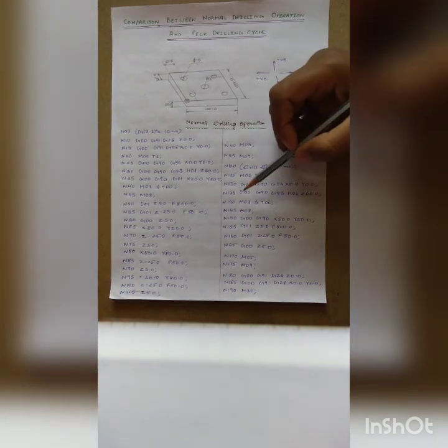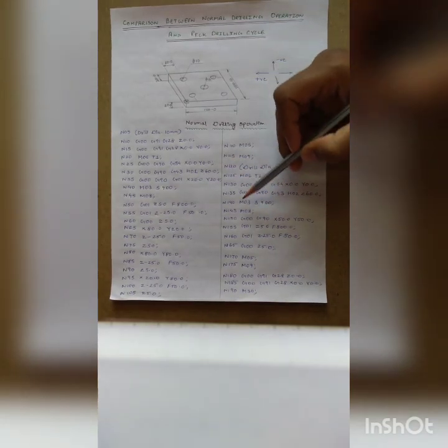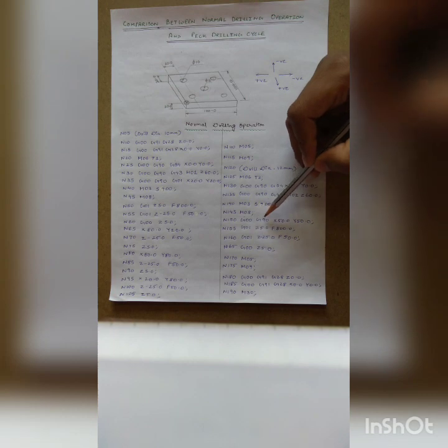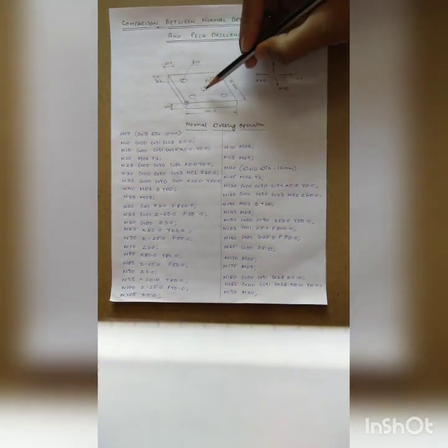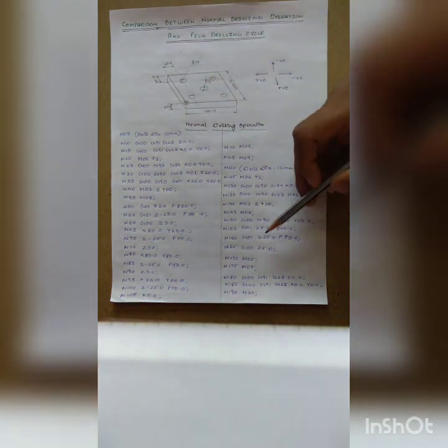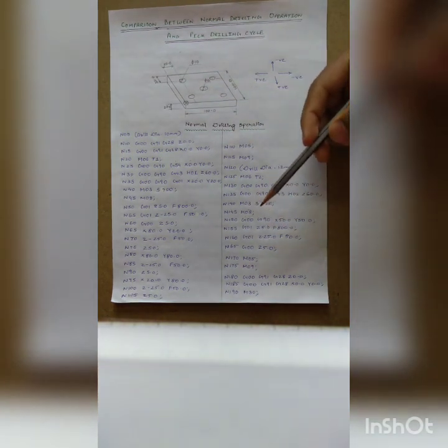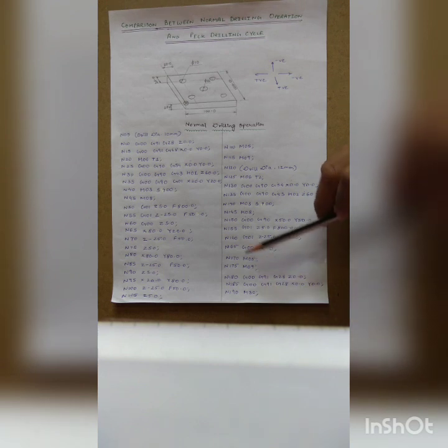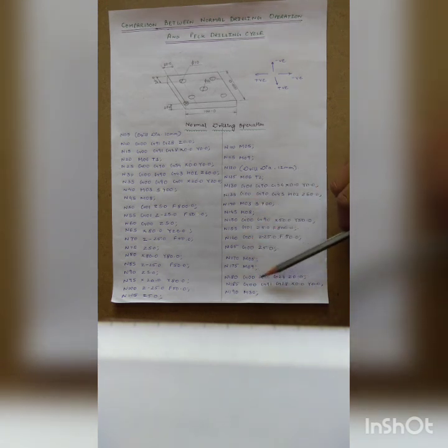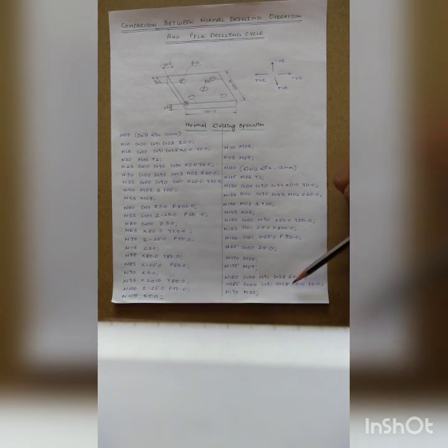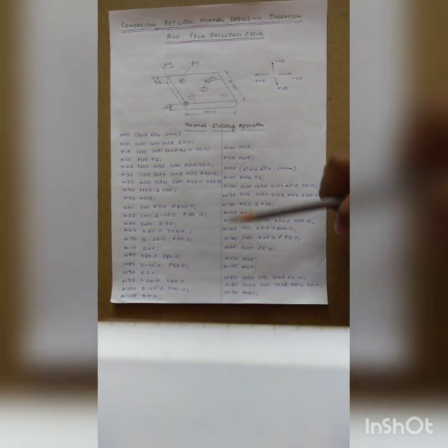Here, after starting the spindle and coolant, by X50 and Y50 the address of the center hole is given. And then by Z minus 25, we are inserting the drill bit inside by 25, and Z5 means return to reference level. M05, M09 means coolant off, spindle off. Then G00, G91, G28, Z0.0, return of the Z axis to its 0 position, and then G00, G91, G28, X0.0, Y0.0, return of both the X and Y axes to their 0 position, and then M30 means program stop and rewind from the first.